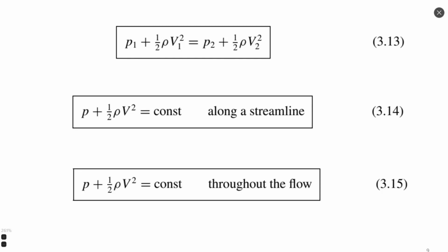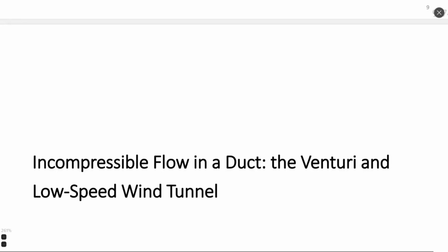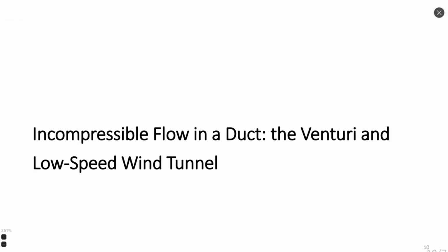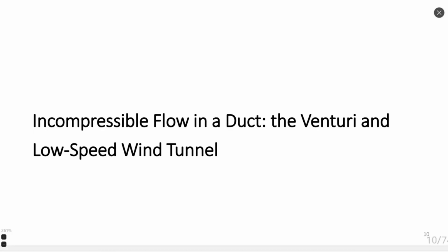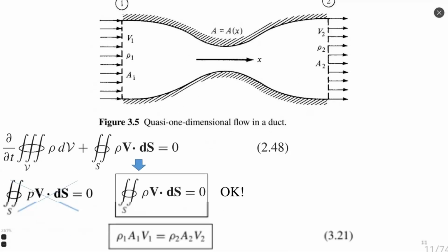And this equation, as we may see here, number 3.13, is also dealing with inviscid flow. You might remember that there is also a viscous form of such an equation, but in aerodynamics we are not working so much with this form, because it can be applied mostly to flow in ducts, and probably fluid mechanics is the best application of such an equation. The Bernoulli equation can be used in several applications.